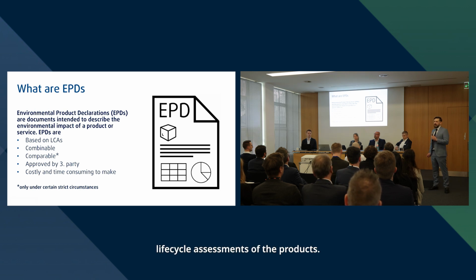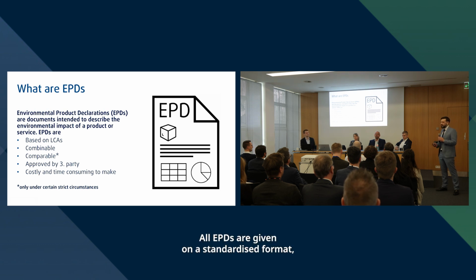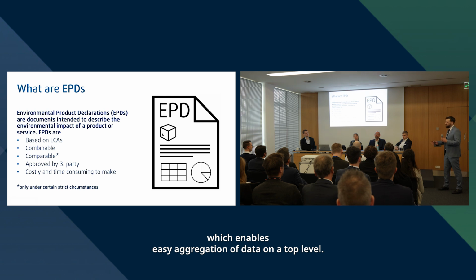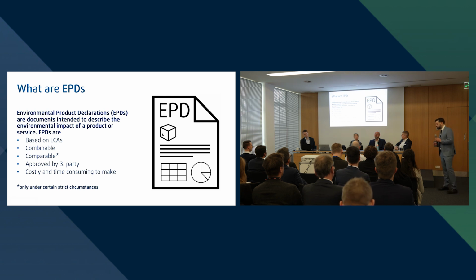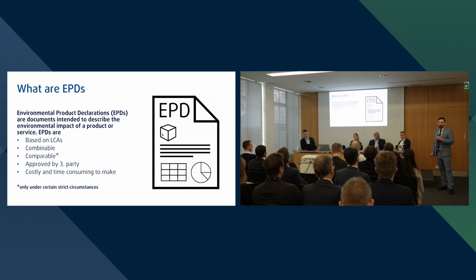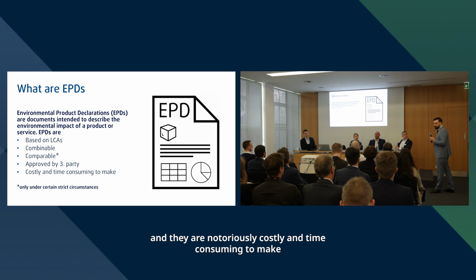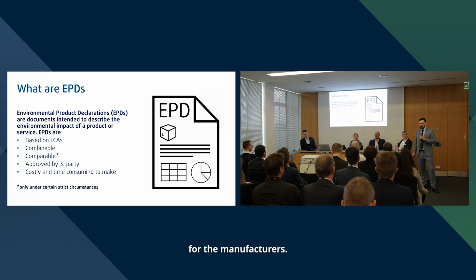EPDs are based on life cycle assessments of the products. They are combinable. All EPDs are given in a standardized format, which enables easy aggregation of data on a top level. They are sometimes said to be comparable. However, this is only true under very, very strict circumstances. They are approved by a third party, and they are notoriously costly and time-consuming to make for the manufacturers.